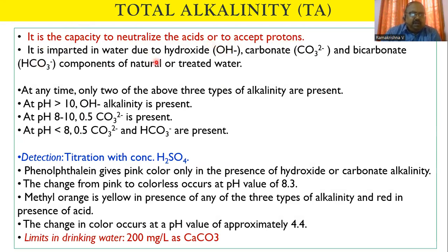So alkalinity is imparted in water due to hydroxide, carbonate, and bicarbonate components of natural or treated water. So alkalinity is defined in terms of hydroxide alkalinity, carbonate alkalinity, or bicarbonate alkalinity. Together, all the components added up are called the total alkalinity.